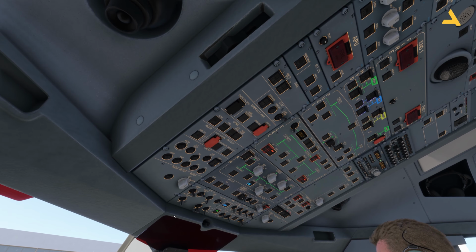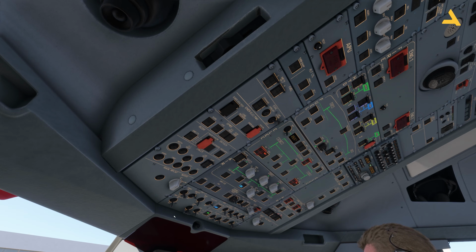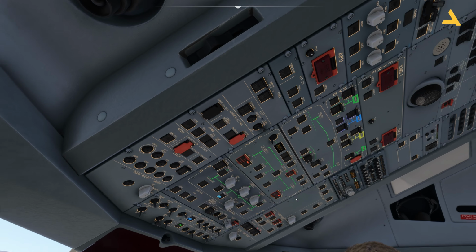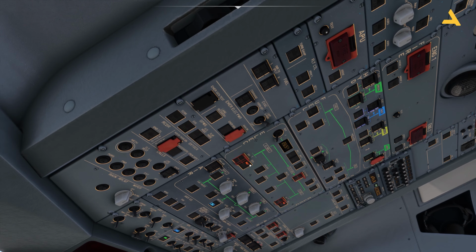Another thing, just want to tell you that in the Airbus planes, if all the buttons are black, it means everything is good. And if anything is white, you have to just get rid of it. And you see this option, fault. This is actually for the generator for the engines. So right now they're showing fault, but once the engines are on, then this will also disappear. That's it.